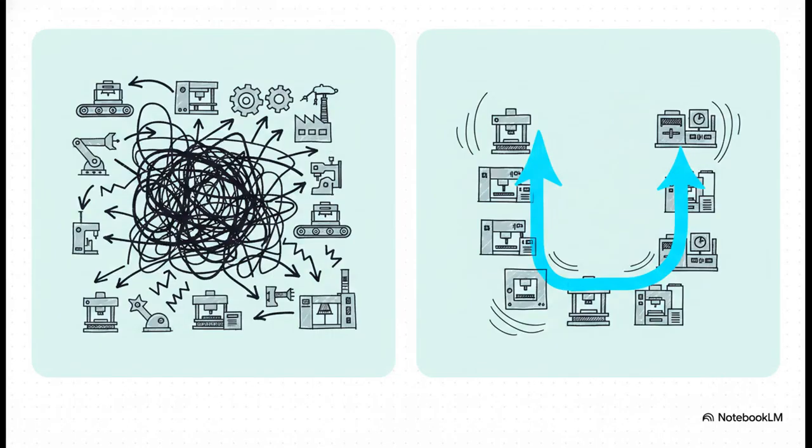The real-world impact of group technology is like night and day. In the old functional layout, all your lathes were crammed in one room, all the drills in another. A single part would have to zigzag chaotically back and forth across the entire building, just wasting a staggering amount of time. But with a group layout, which you might hear called cellular manufacturing, machines of different types are clustered together into a single, dedicated cell, built specifically to produce one family of parts. It transforms a random, chaotic maze into a sleek, incredibly streamlined powerhouse.